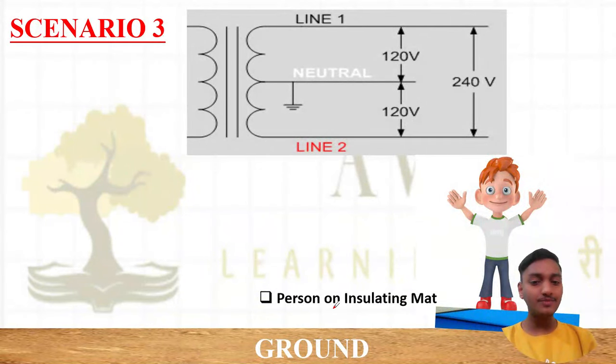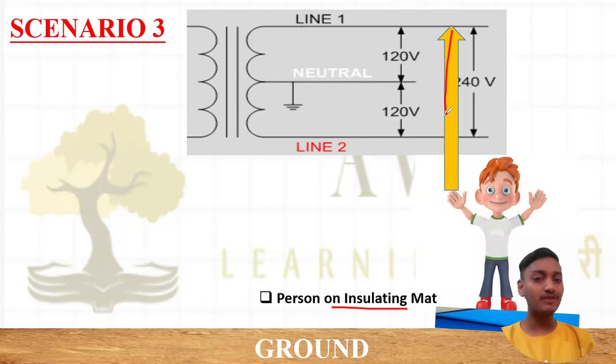Now the third case is where the person is on an insulating mat, a highly insulating mat. If the person is on the insulating mat and comes in contact with the electric wire, what will happen? Current will try to flow, but there is a very strong insulating mat, so current will not be allowed to go through. Because of the high insulation, it offers high resistance, and the person will not feel anything. That is why we always prefer to use shoes or an insulating mat when working on any electrical equipment. That is why it is generally advised.